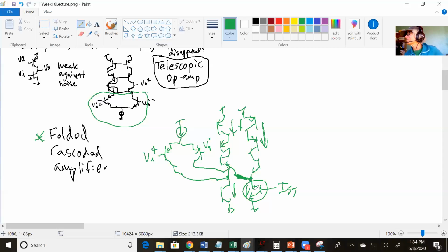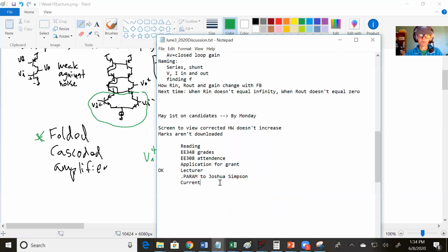And I know that just went way too fast and probably made no sense. But if you're ever designing something and you have too many transistors between the supply and ground, look up folded. See if you can fold that circuit. Put the input part of the circuit, pull it out to the side, and somehow connect it up so you get the same behavior of your circuit. And again, I'll do a video.